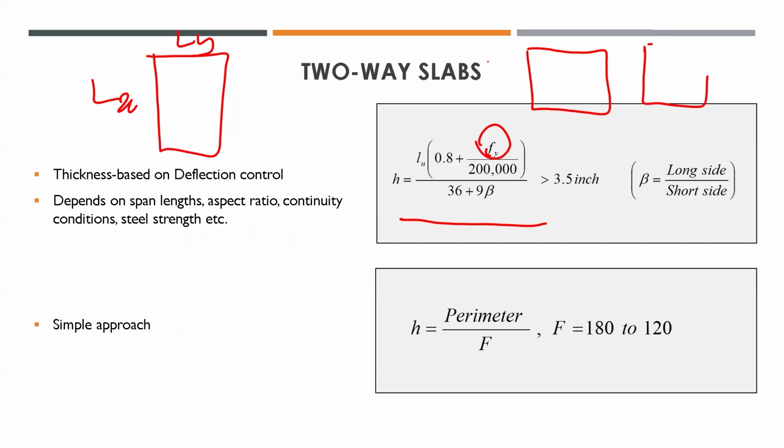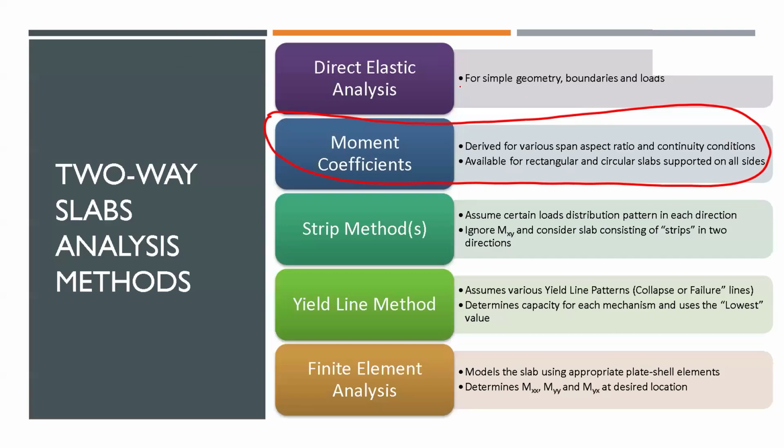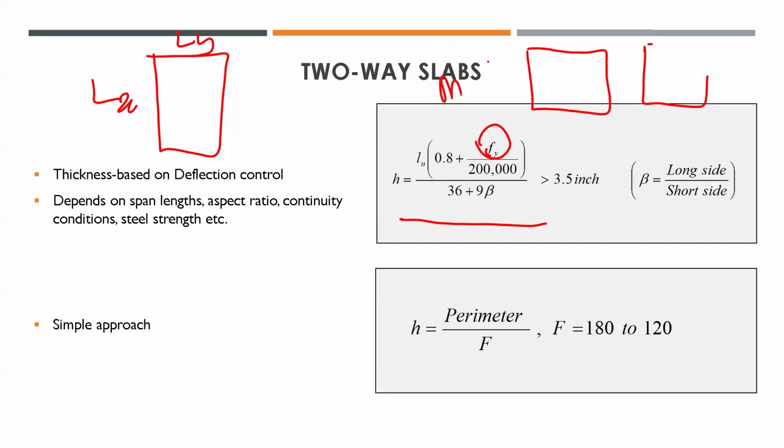So this is, let's say, moment, what's happening? Moment, and then this is, I'm using some steel Fy1, which is low strength. This is high strength steel, Fy2 equal to 400, and this is 200 megapascal. For the same moment, for the same thickness, this one will give me more reinforcement or less reinforcement?